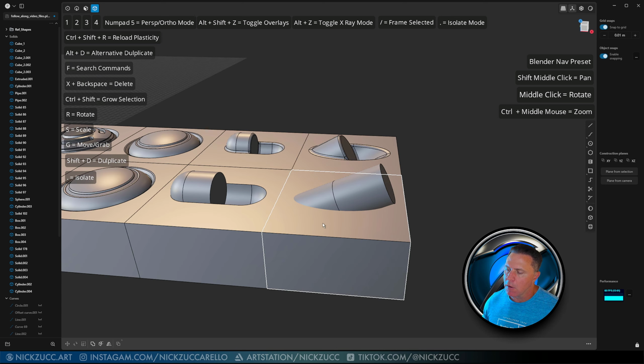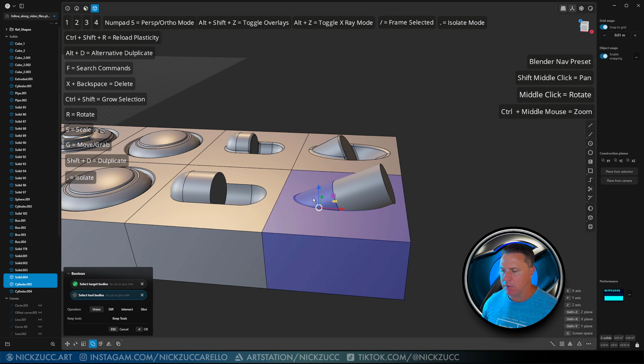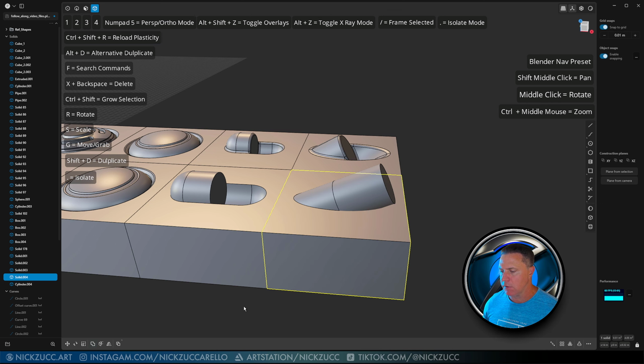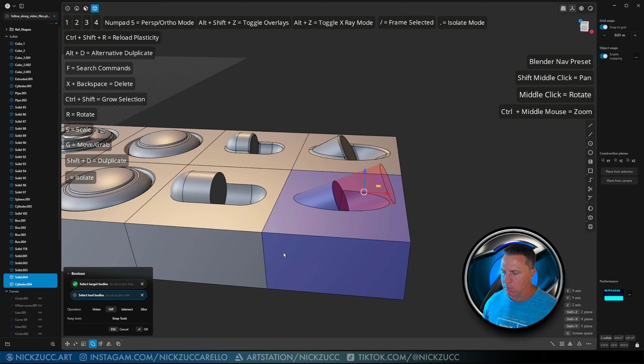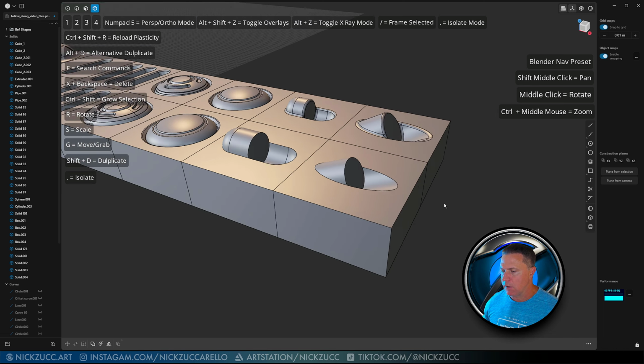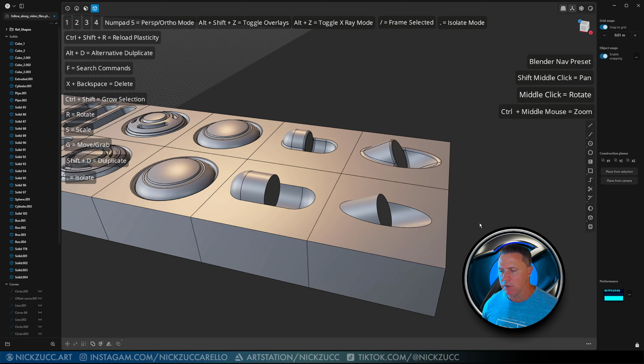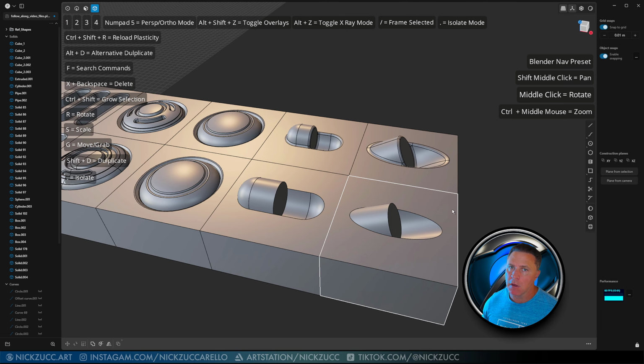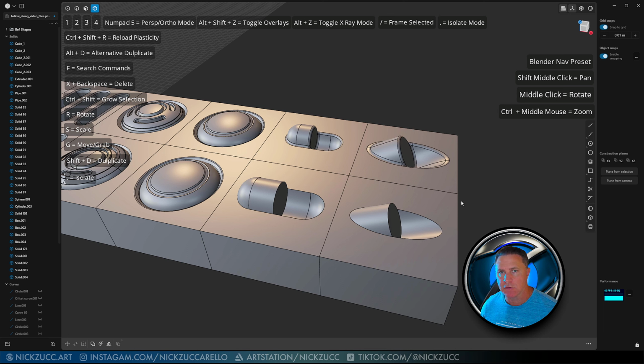There we go. Okay, I'm going to select this and this, tap QQ and Boolean, hit OK. Select this one, hold down Shift, select this, Q, and hit OK. And now we've built these shapes that we've got here. Okay, so that's not a big deal, very easy. The next part is going to be more difficult, where we start to go and we start to try to chamfer or fillet these edges on here.